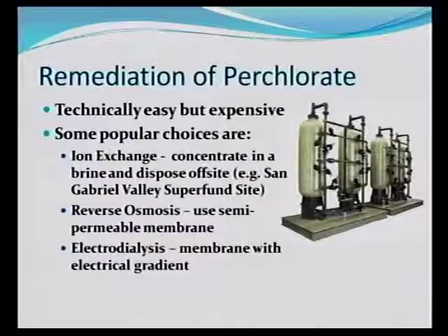Basically, these are methods that are standard water treatment methods for any water, drinking water that's extracted from groundwater. So even if you're in a clean system, generally these ion exchange, osmosis, electrodialysis, they'll be used for cleaning up drinking water, depending on the quality of the drinking water. They're not used everywhere. So this can be done. As it turns out, it's quite expensive. For example, in these ion exchange resins, it's hard to get the perchlorate back off the resin.